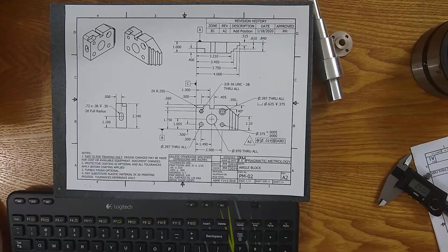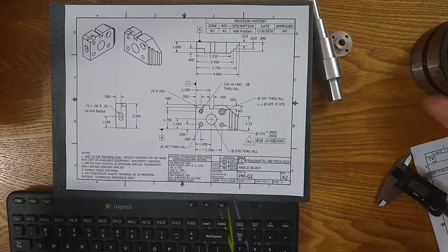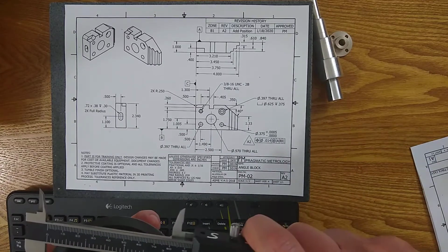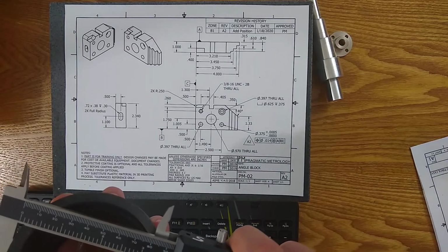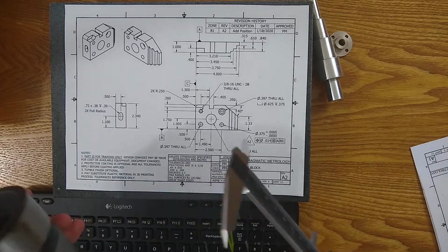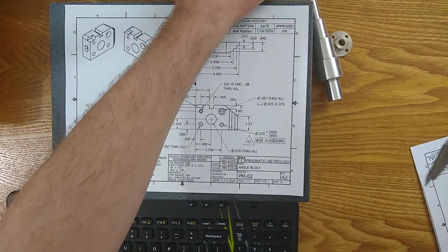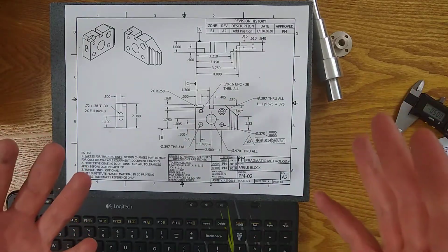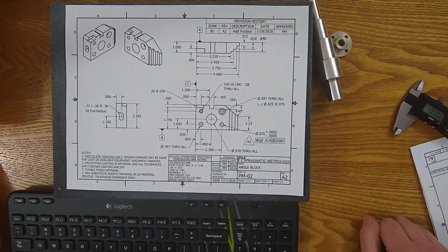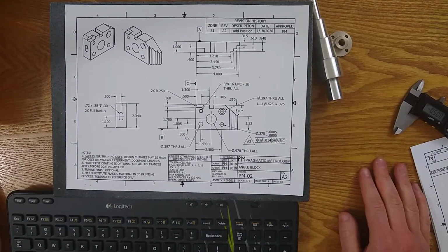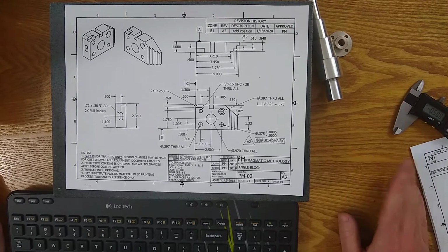That's why sometimes when I'm teaching, I say, yeah, there's a form error for that. You checked your diameter in one spot and it passed. But what about the other spots? Because it's not perfectly round. Nothing is perfectly round, except gauges maybe, but you can't assume that. You have to look. If it's in tolerance 90% of the time, and some of the diameter is out of tolerance, it's still not going to pass. So that's something you need to look for.